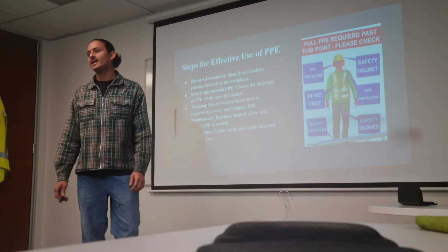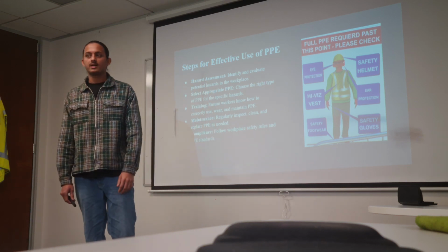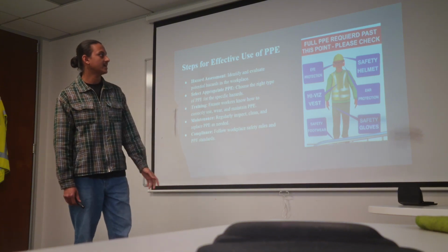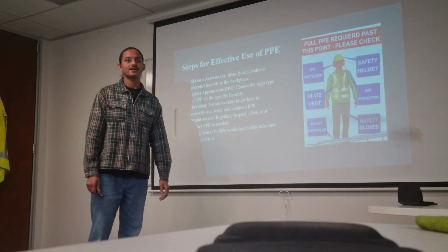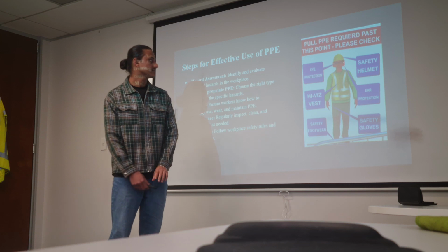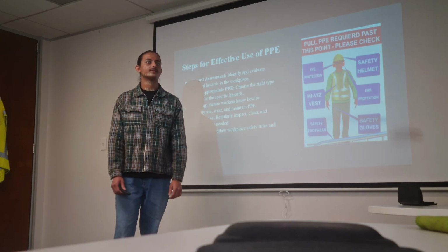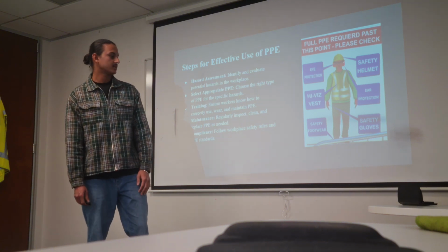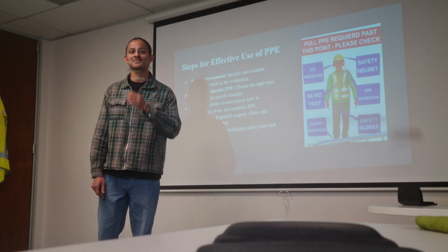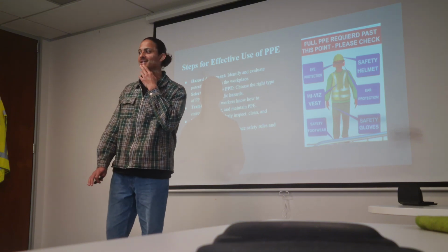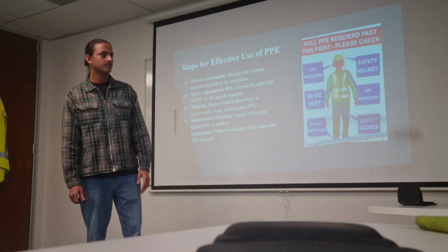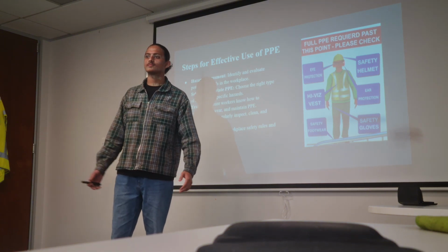PPE ensures that if any hazard occurs, it will cause minimum damage to the workers by using a safety helmet, which protects the head of the worker from falling objects, eye protection from small particles entering the eye which may lead to eye damage, ear protection for noise pollution, high-visibility vests to ensure workers' chests are protected, safety footwear to ensure nothing harms the foot, as in the workplace and construction place different things are laid down like nails and small particles of steel, and safety gloves to handle the metal or any aluminum doors very carefully.